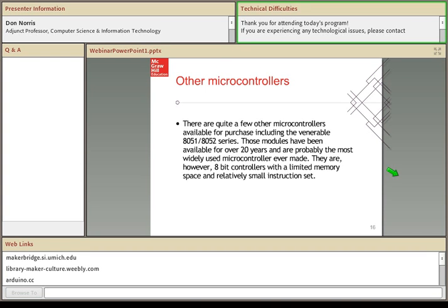In fact, I would say without hesitation that there are more 8051 and 8052 series out there than all other microcontrollers combined. Intel makes this, and they still do make them, but they're not recommended for new projects. These new systems I was just talking about have far more capability. They are 32-bit processors versus these 8051s, which are 8-bit processors. The 8051s will be around for a good number of years to come because of all the legacy products that exist.